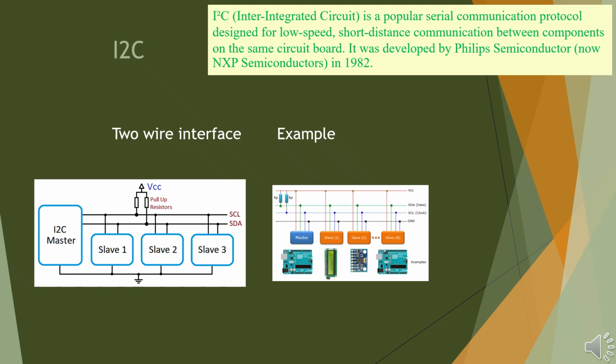One key advantage of I2C is that it allows many devices to share the same two wires, reducing wiring complexity significantly. For example, you can connect an OLED display, a temperature sensor, and an accelerometer to the same SDA and SCL lines of a microcontroller. This makes I2C particularly well-suited for compact embedded systems, sensor arrays, and mechatronic projects where PCB space is limited.